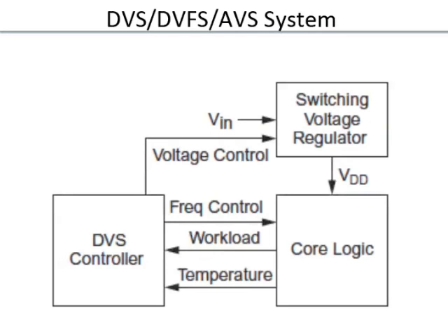We'll look at that in the next class, but the overall system looks like this, of a dynamic voltage and frequency scaling, or adaptive voltage scaling system. No longer is the supply voltage to the chip fixed at 1.2 volts or whatever. You have a voltage regulator which you can control. There will be a control system sitting on the side which adjusts the voltage based on the actual throughput requirement.